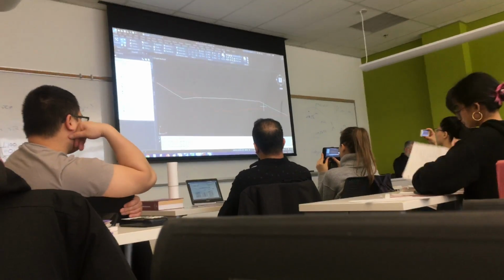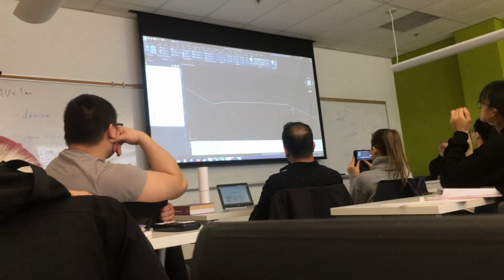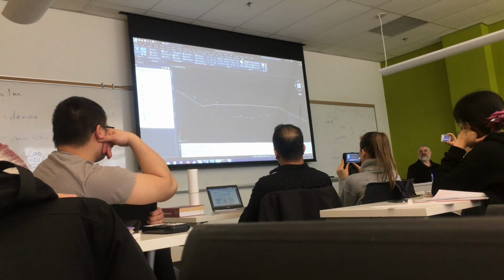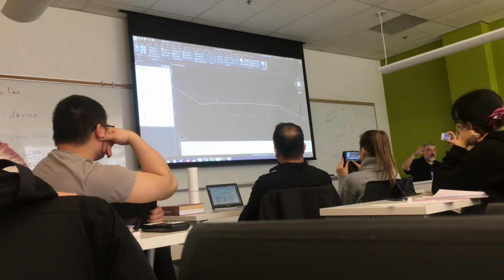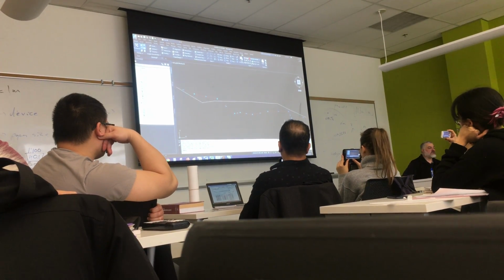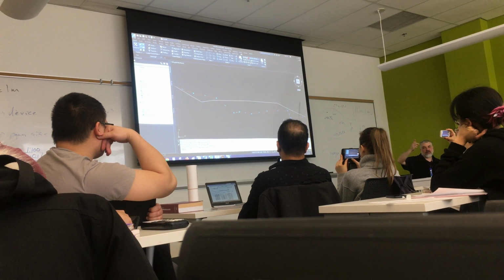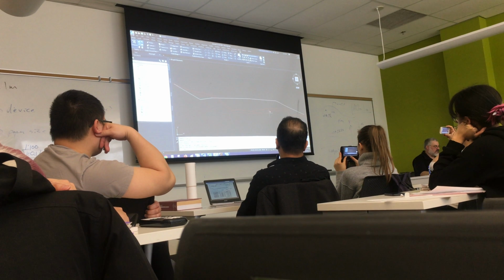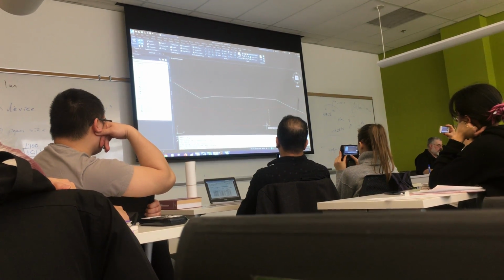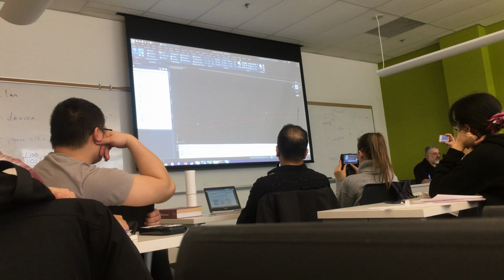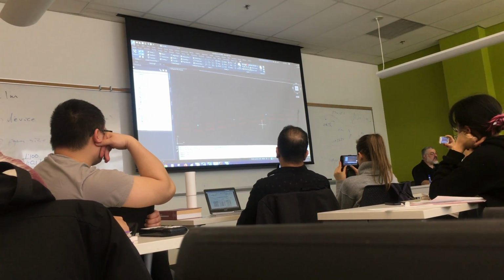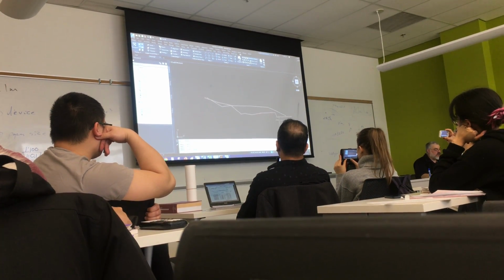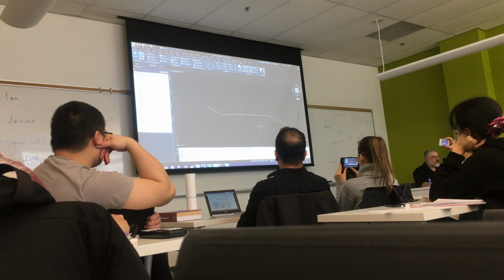Okay? So, first thing you do on a construction job is strip all the topsoil. So if this is the existing ground and you have the geotechnical report, you can get a sense of what the top layer from your boreholes is, right? How much organic, how much topsoil you have. So you can actually lower that vertically for the topsoil depth. Right? So let's assume we have a foot. So I'm going to make a copy of this straight down, 0.3. Right? So if you take away all that information, that's your starting condition. Right? If you take away all that topsoil, that's your starting condition. Strip. And then this is your pre-grade, right? Without the construction materials. So this is what you have to build.